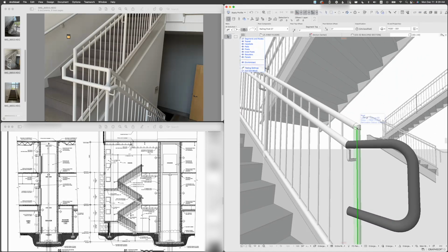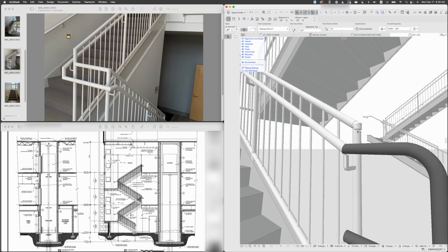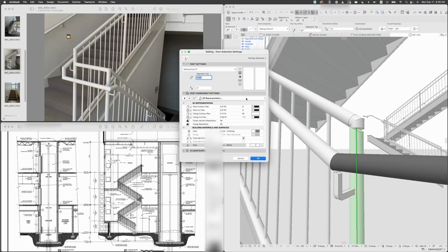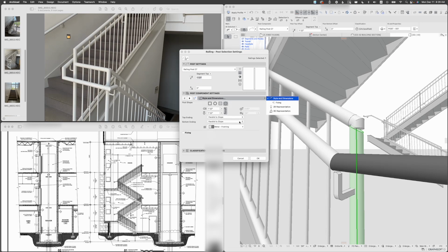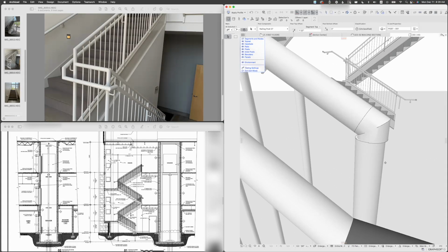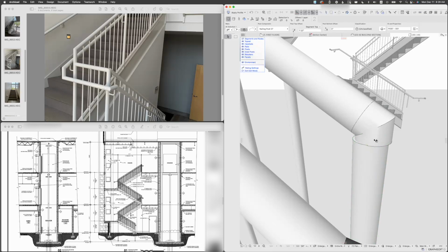We should just click on this post and try to move it down, and now you see there's another problem we have to deal with. We have to select this vertical post, go to the style and dimensions, and change the top ending to horizontal, and voila, it's working. Well, so see, it's almost clear.